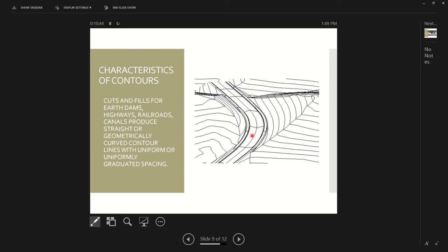So I can look at this map and say, this is the low spot on the road because the V's are pointing up. Inversely, in the ditch here, the V's are pointing this direction, so it means that the low spot's down here somewhere, and this is flowing water down this way. If that makes sense. All right.